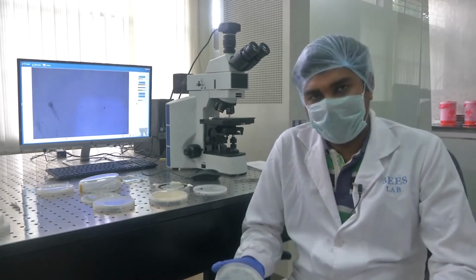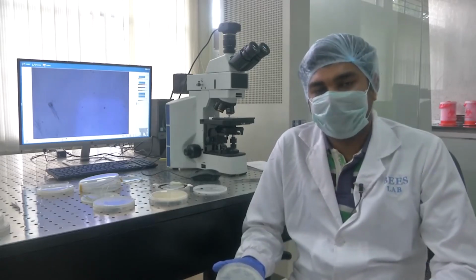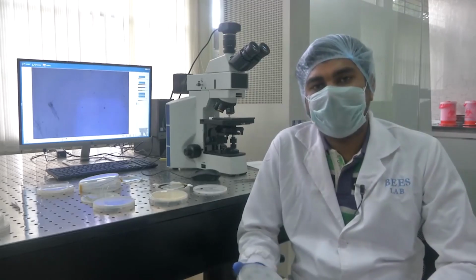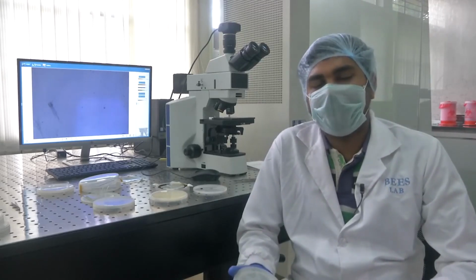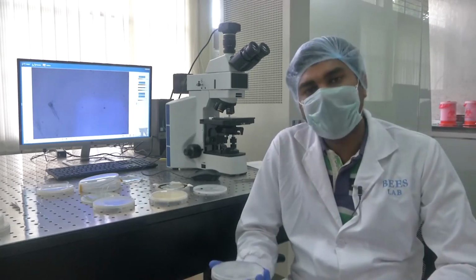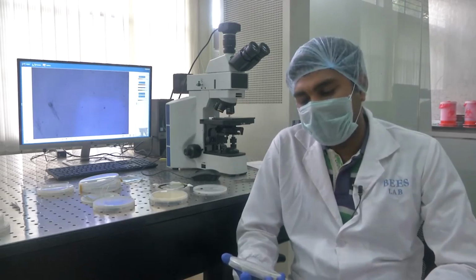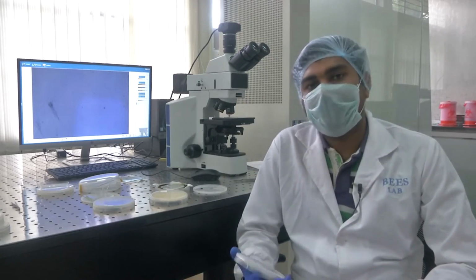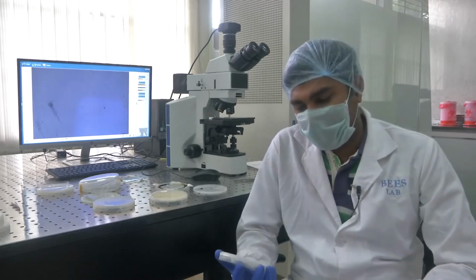Then we saw a patterned glass substrate with gold electrodes. We saw it under the microscope. We saw how the features are visible as we go to higher magnifications. Okay. Now I will show you another design which we have made on a silicon wafer. On the silicon wafer we have deposited platinum, and we have used the lift-off process to make the features.